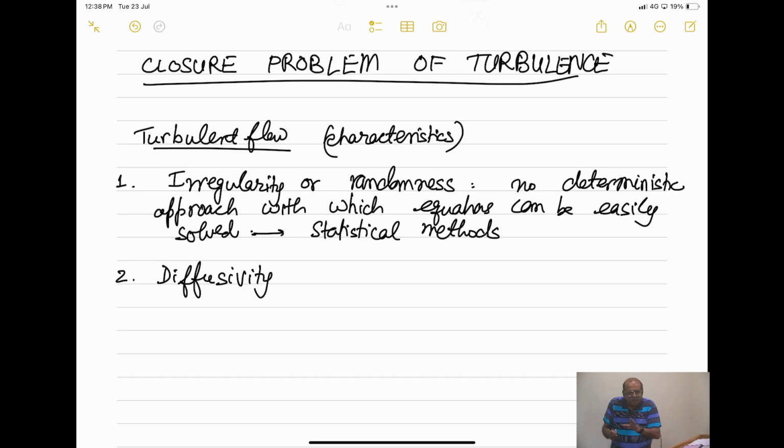So in this equation, there is no velocity, it's only temperature. There we have a constant K by rho C, which comes in front of del square T. And that is what we call diffusivity, thermal diffusivity. So this K by rho C term is the one which tells how fast the temperature will diffuse. And we call it molecular diffusivity because there the diffusion is being done only by the fluid and its molecular properties. But in turbulent flows, what we find is that there is